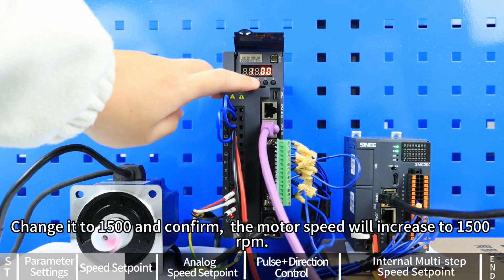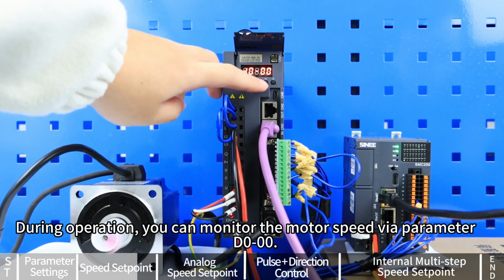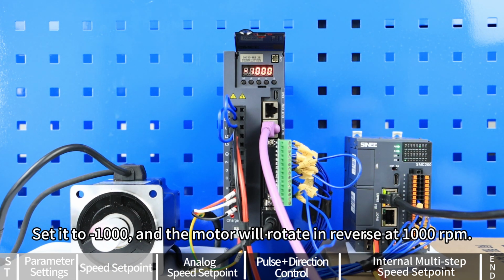Change it to 1500 and confirm. The motor speed will increase to 1500 revolutions per minute. During operation, you can monitor the motor speed via parameter D000. P201 can also be set to a negative value, in which case the motor will rotate in the reverse direction. Set it to -1000, and the motor will rotate in reverse at 1000 revolutions per minute.